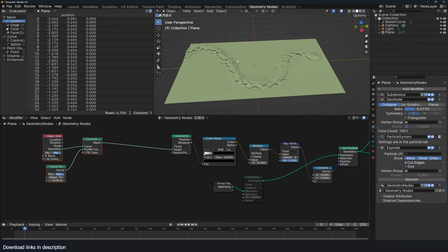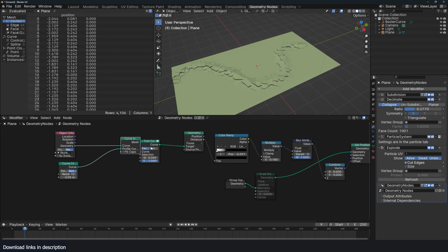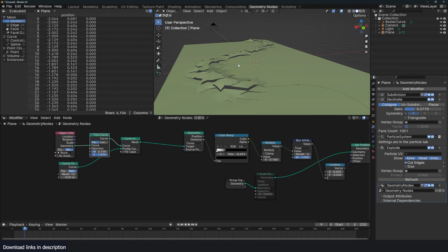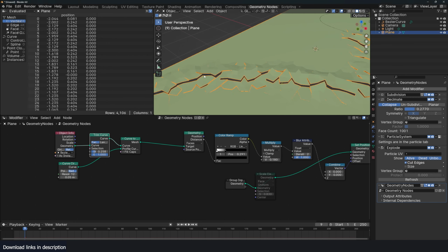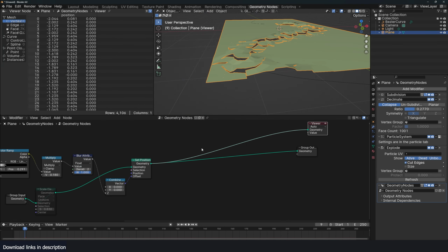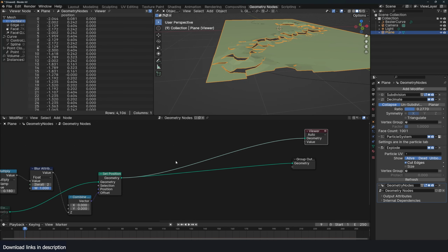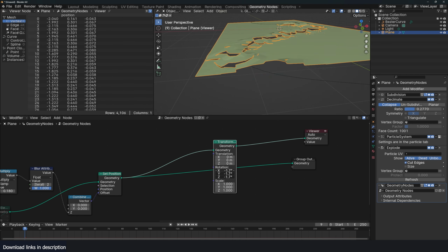We are almost done because right now you can just even add a curve trim here before you convert this to a curve. So around here, and you get something, but we are not done yet. So we can rotate the individual pieces a little bit depending on how close they are to the curve. And unfortunately, there isn't a way to do that easily. For example, if I wanted to rotate this, since this is a mesh, the only way to do that is by using the transform, but that will rotate the entire mesh.